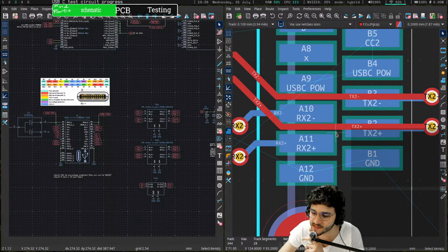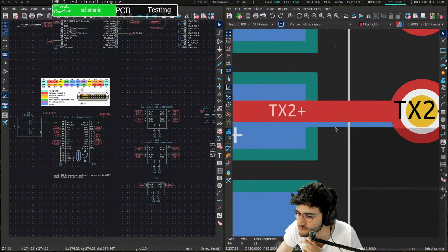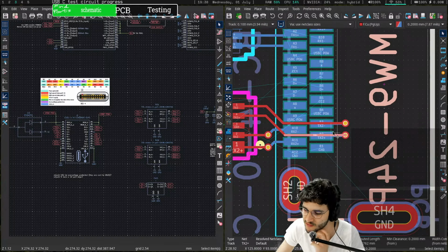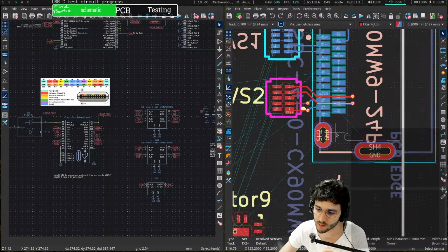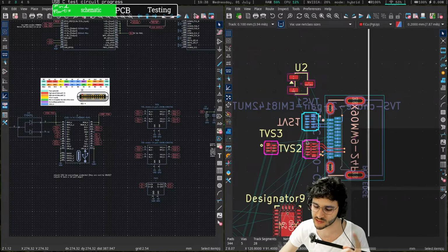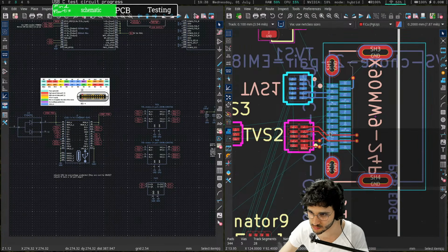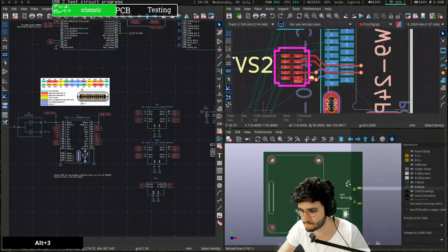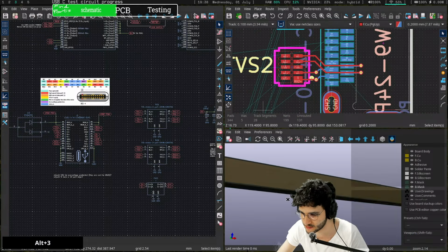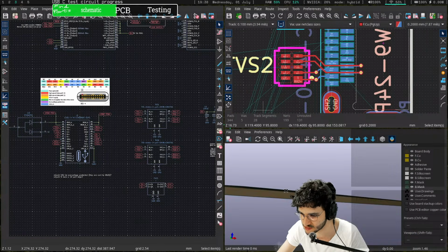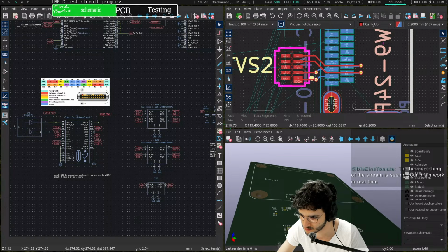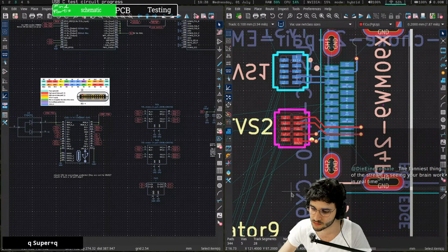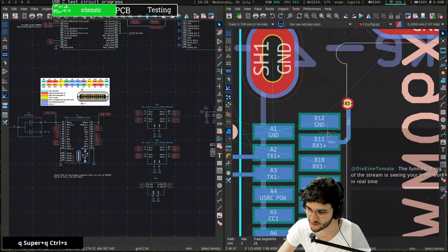And also, big assumption here, I assume that having one signal on top of the other is not a problem because I will have 2 copper layers and a core of laminated material between them. Right? There's thick stuff. So I think it should be fine.